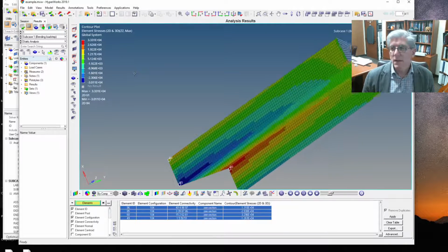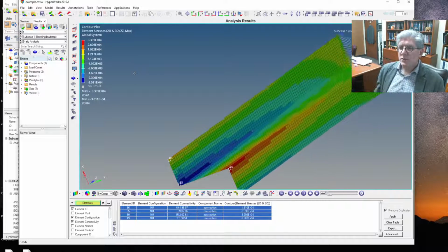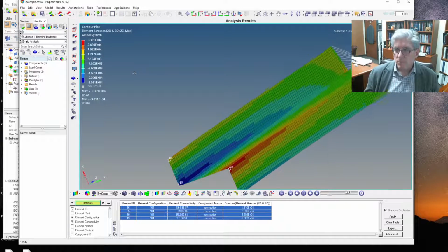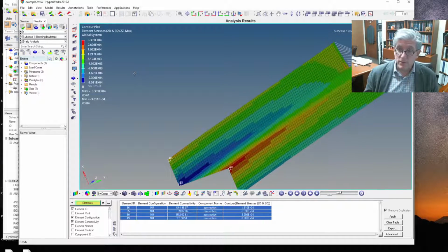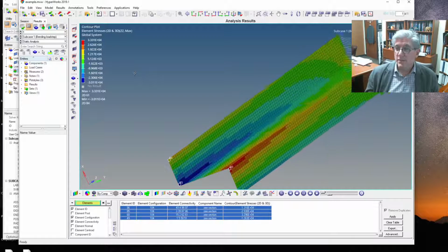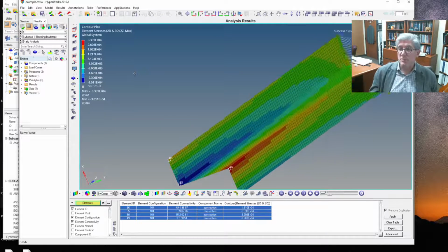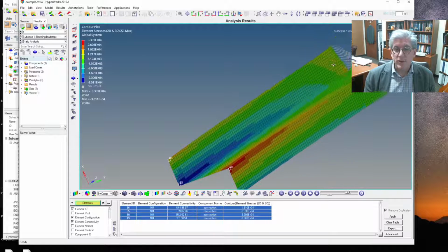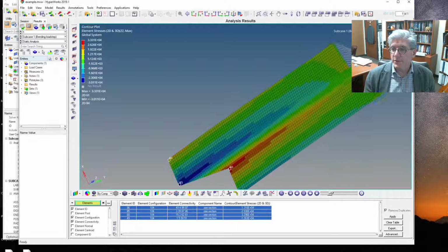And so keep track of those big steps: define the materials, the property cards, make the mesh, boundary conditions, and then load step. And then you shouldn't have too much problem solving these things. Like I said, to start with, we're just going to be using these simple shell element meshes. If we're putting forces at the end, use the RBE3 element, okay? And you should be good from there, okay?